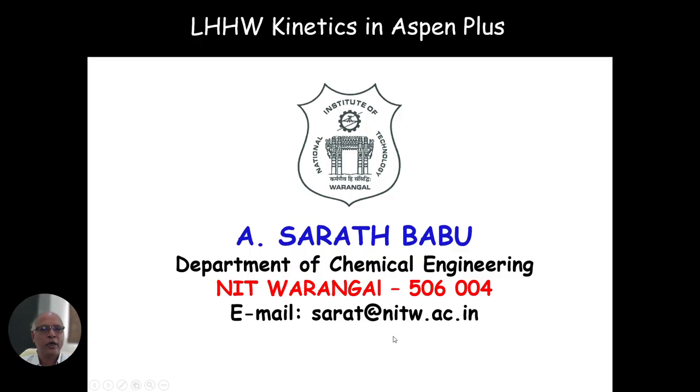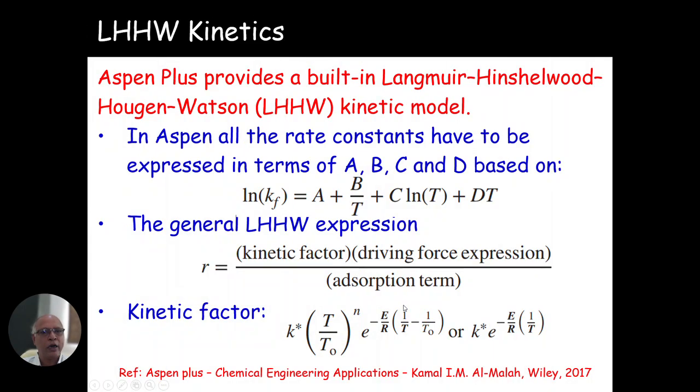Now, typically when you look at Aspen, it has got a built-in model to represent these kinetics given by Langmuir, Hinshelwood, Hougen-Watson. In short, we call it the LHHW kinetic model. As you are already aware, this kind of expression will result especially when you carry out gas phase reactions catalyzed by solids. Typically the rate laws are divided into three factors. The first one is known as the kinetic factor, the second one is known as the driving force, and the third one, whatever you have in the denominator, is known as the adsorption term.